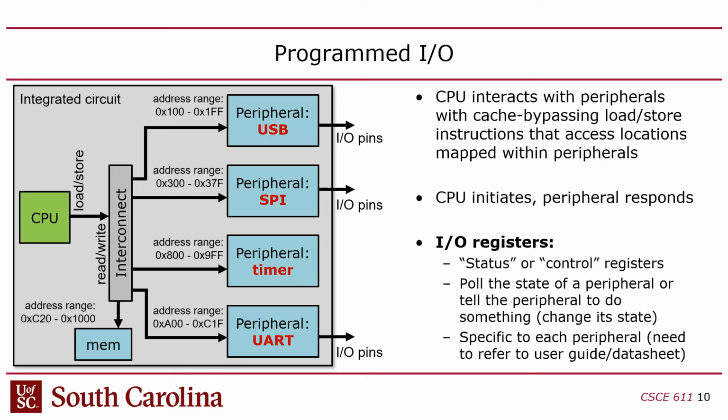So the CPU would talk to this USB peripheral using programmed I/O, as I described, but then it would go off-chip with a USB bus to talk to an off-chip peripheral. So this thing is a bridge, basically. What it's doing is bridging this programmed I/O interface between the CPU and this circuit with the USB interface that then goes off-chip, right?